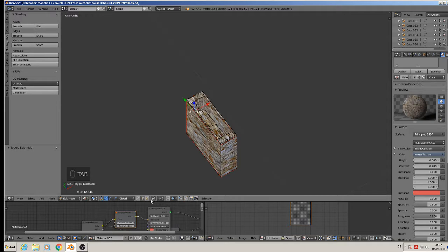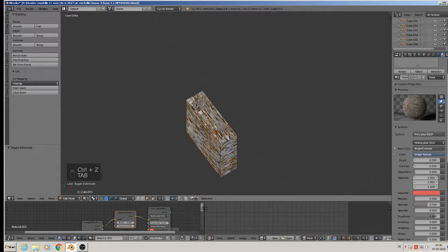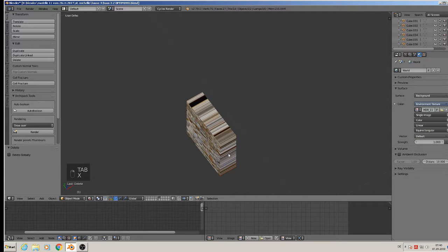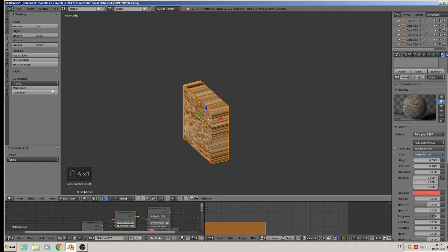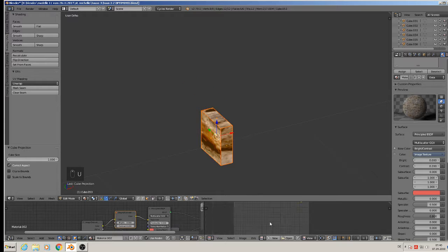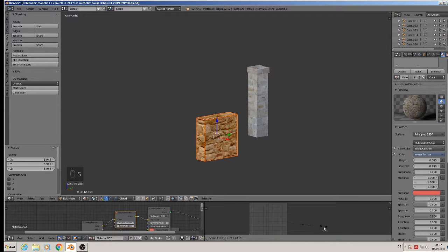So we take here simply one from them, Shift D, P to separate the selection. Now we have only the plane here, and that we can extrude outward and delete the other stuff. So we only have that left. We simply mark that seam completely, and you unwrap cube projection, go here and simply scale it up, and then we have here our smoker again.